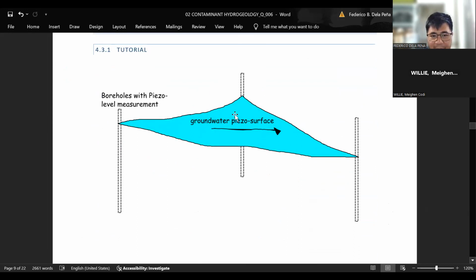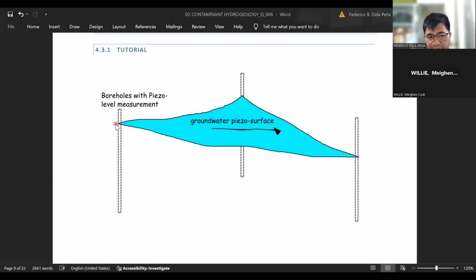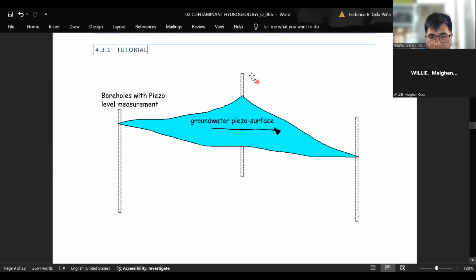Okay, 3-point problem: you have 3 points, or actually a minimum of 3 points, with different elevations indicating a sort of contact, like a bedding plane. And then from those elevations of bedding planes or geologic contacts, you want to determine the strike and dip of the bedding plane surface.